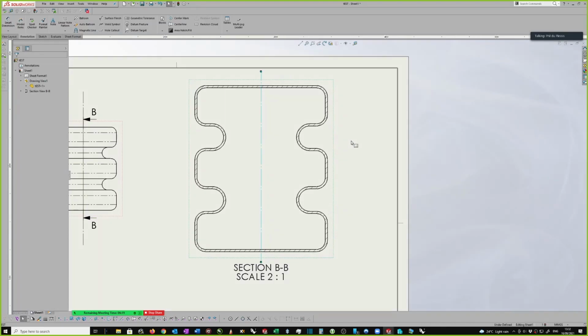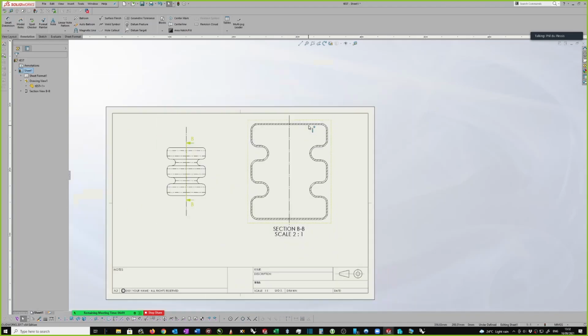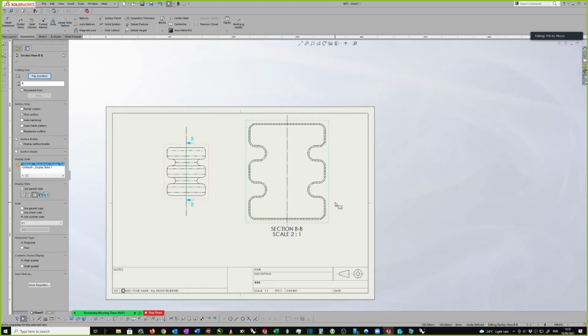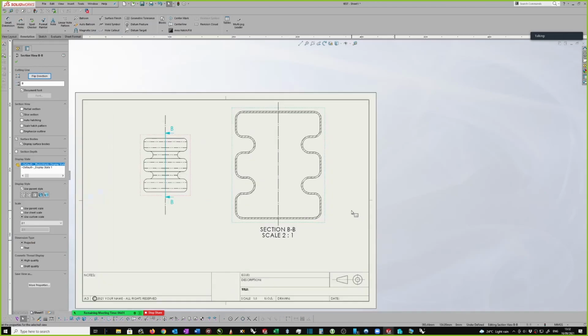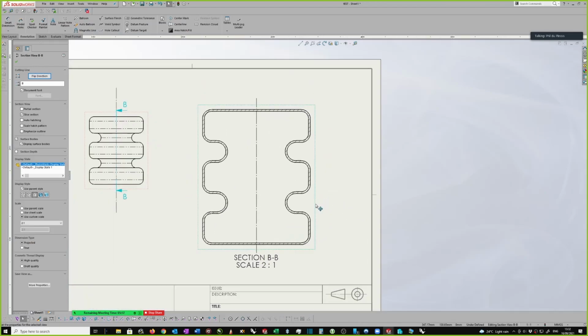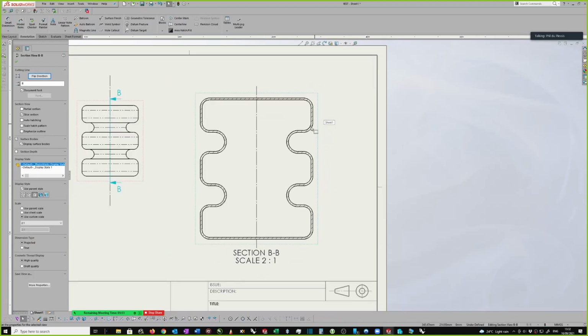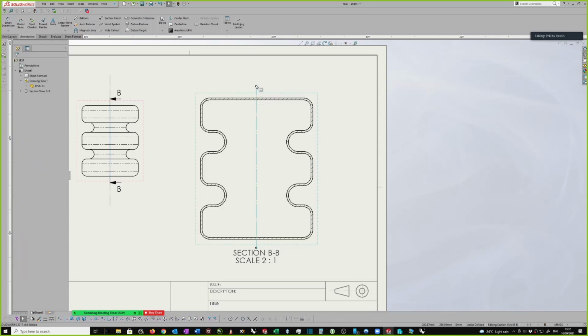The temptation here is to see that radius and that radius as separate radii, because you've got 2 radii. You've actually just got 1 radius. All of these radii on one side are just single radii. The other thing, let's just get this to break alignment. Okay, so the other thing about this, I'll show you the radii thing now. The other thing about this is just to quickly talk about dimensioning across center line.